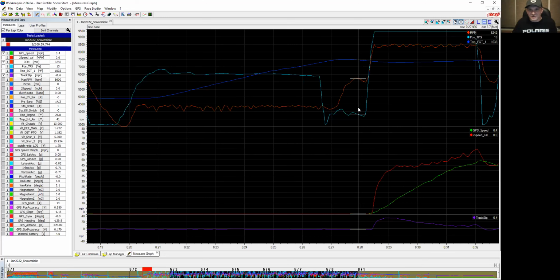And then your EGT temperature at takeoff really dictates your RPMs off the line. Up or down a couple hundred degrees, and you're up or down a couple hundred RPM on your initial launch. But then it's just that straight line across.